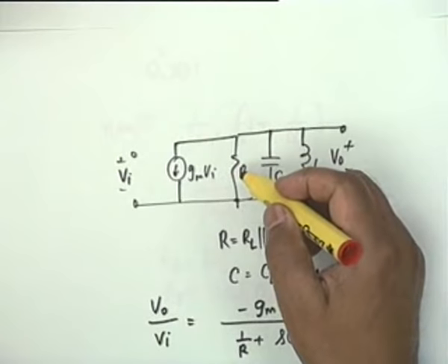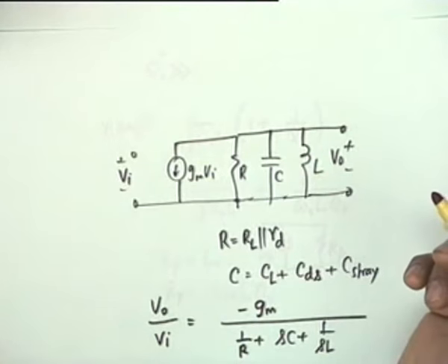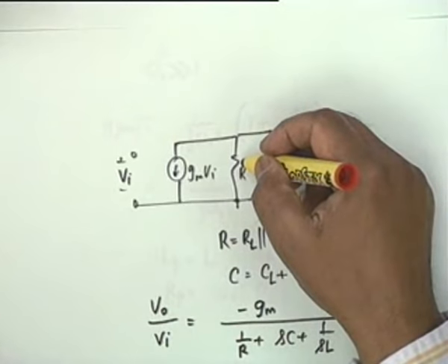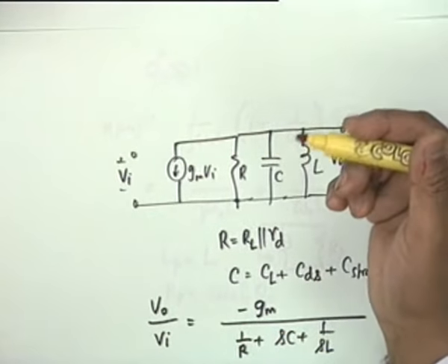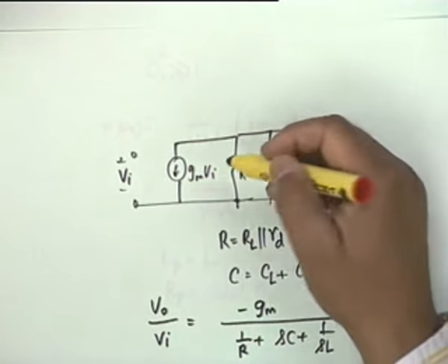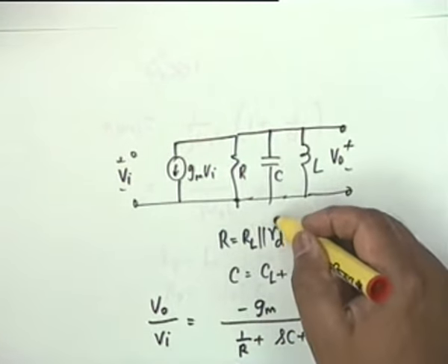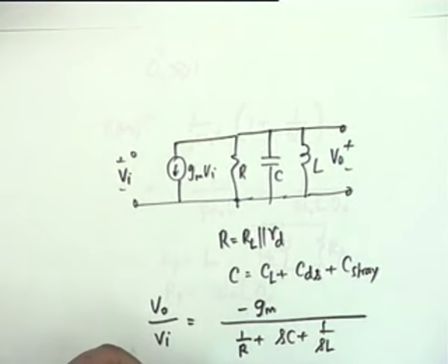We have to go back to the original circuit. What was your question? If I need R as large as possible, why do I insert this resistance? Okay, any answer? What is this resistance? This is the capital R sub capital D. You require a resistance to bias the FET, and it is that resistance in parallel with the dynamic resistance. The resistance is inevitable. It shall be there. It can be large, but it shall be there. Okay.